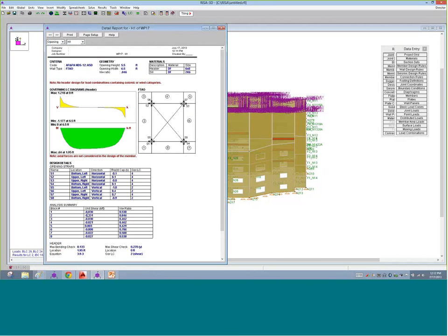So for block number 1, we can see what the unit shear was across that. We can see 2 goes up here, then 3, 4, and as you look at this, you can see what the maximum is. This is a lightly loaded wall, but it looks like maybe 3.1 is the highest number I have here, 31 pounds per foot running across that. That's your worst case, and that's maybe in the 2 element right here. And so when we go back, this header gets designed just like it got designed in perforated.